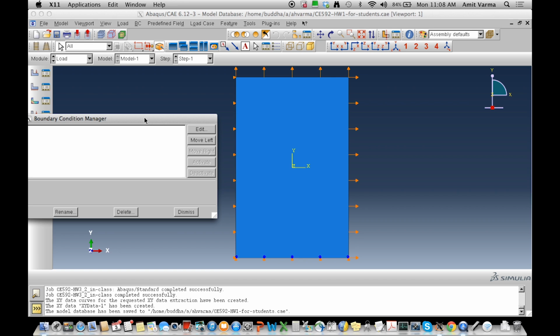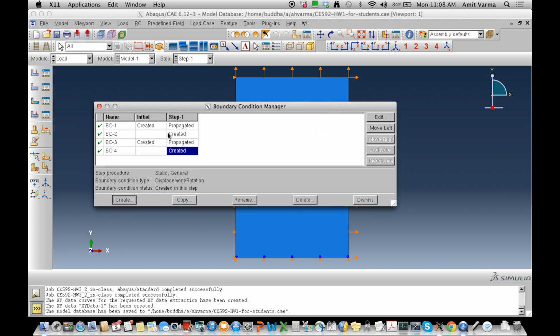If I wanted to apply 1% plastic strain first in the vertical direction, and then apply a 1% plastic strain in the x direction, they would have to be two different steps. I would have to apply them one after the other. But I'm going to do that as well. That will be the next analysis I do. Right now I just want to continue with the proportional loading criteria.